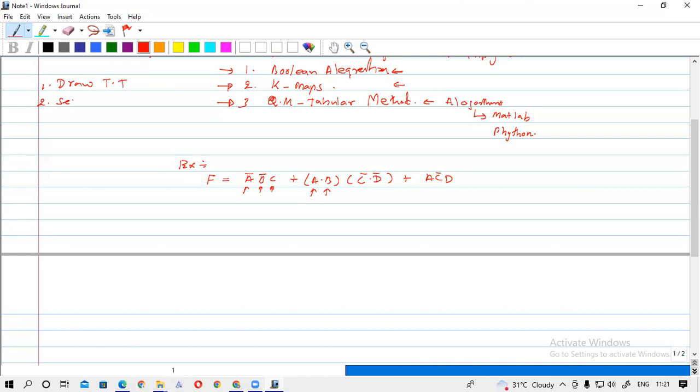And we select the outputs that give ones. Can you remember? We select the outputs that give 1. Then these ones we combine using the AND function with these inputs. Then all those terms we combine using the OR function, the OR gate.